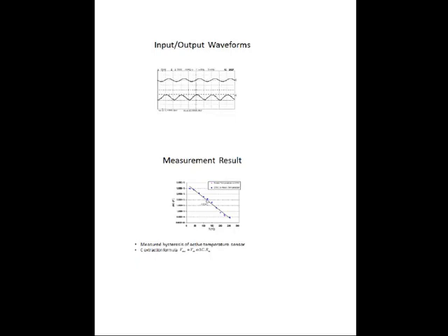And I mean, this is the basic calculation way to extract your capacitance variation. This is your input voltage. This is your impedance of this capacitor, and this is the Rn. So we divided by your impedance times the trans-resistance gain gives you the output. So we had 0.28 picofarad at room temperature, the capacitance, and at 300 C it became 0. So it's about 300 femtofarad change over 0 to 300 C.